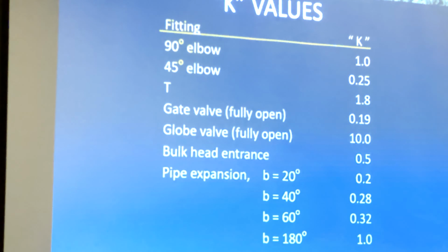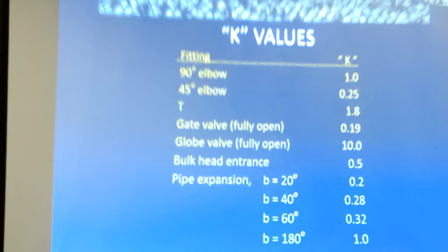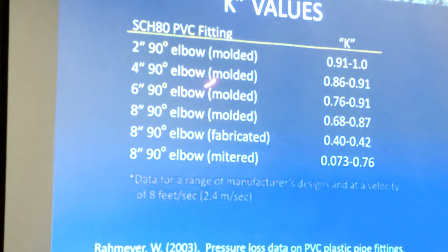Unfortunately, that's a long time ago for iron pipe. And nowadays, we have more precise values for K from folks in the heating and chilling industry, because they tend to have higher velocities and they'll have smaller pipe or more fittings. So they're really interested in how the friction is in these coolant lines.